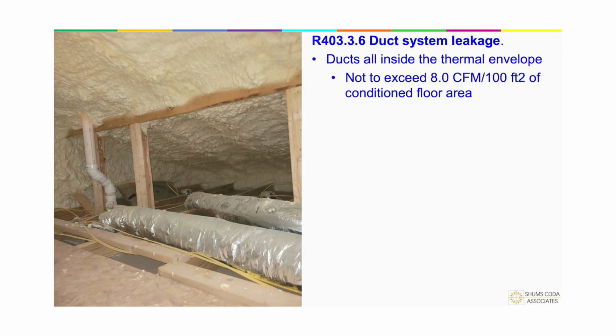Now, here's the fun one. If you have ductwork that's located inside the thermal envelope, in the past it was exempt from being tested. You didn't have to do the duct leakage test. Now you are required to do the duct leakage test. You just get the ability that it gets to leak an awful lot. You get to go all the way up to 8.0 CFM per 100 square feet of conditioned floor area.